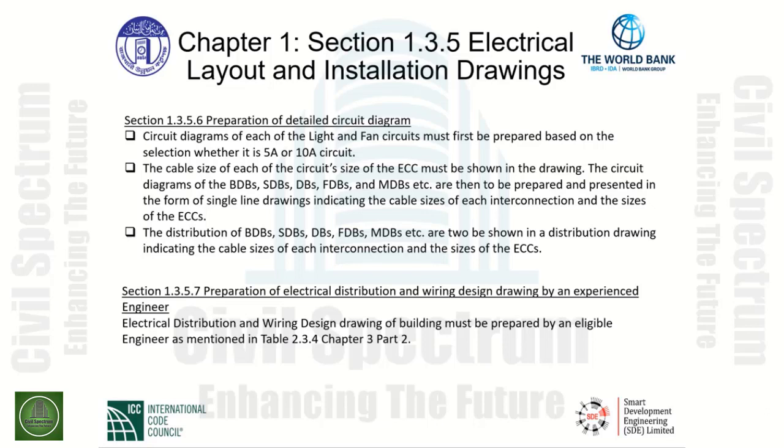The circuit diagrams of the BDBs, SDBs, DBs, FDBs, and MDBs, etc., are then to be prepared and presented in the form of single-line drawings indicating the cable sizes of each interconnection and the sizes of the ECCs.